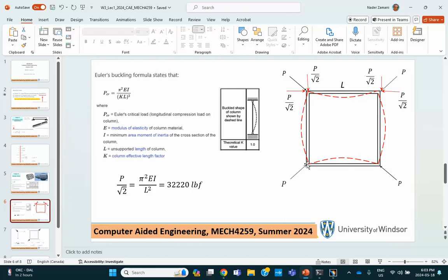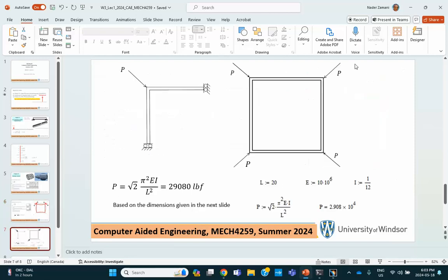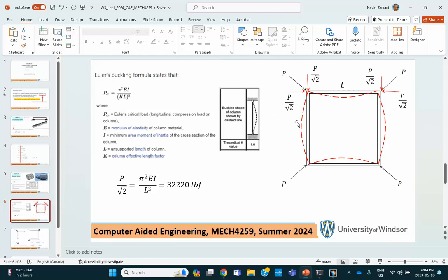It's this frame structure that we are applying a compressive load to, as shown. Let me go to the next slide. We're going to come back again to this. We're going to compress it like that. And when you think about this configuration, and if you're only interested in the buckling, symmetric buckling in the plane, you can see that essentially we have a cantilever, we have a beam here, pinned, and it buckles. So it looks like it fits this description.